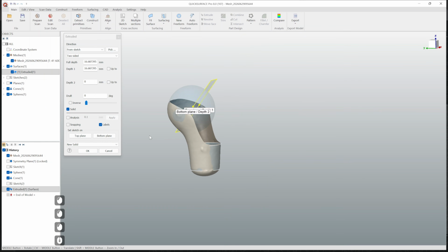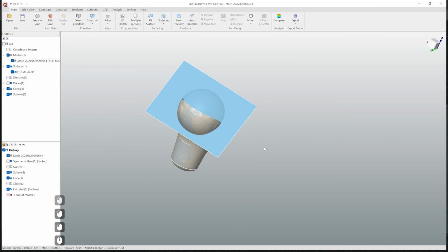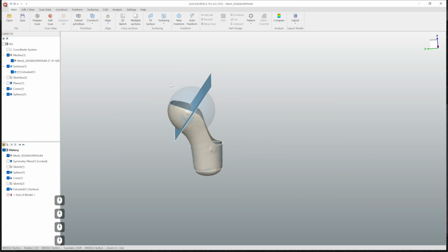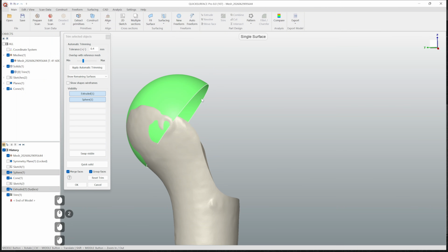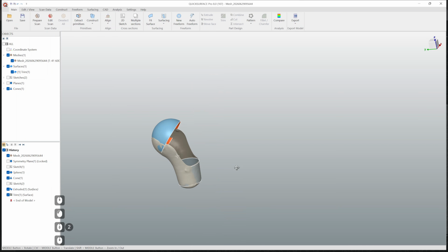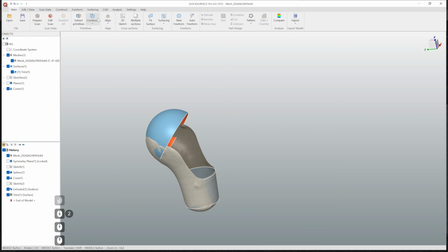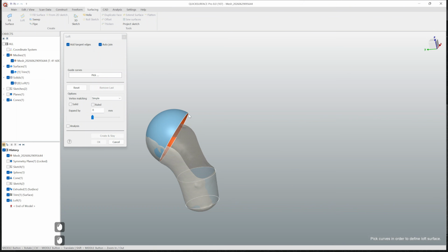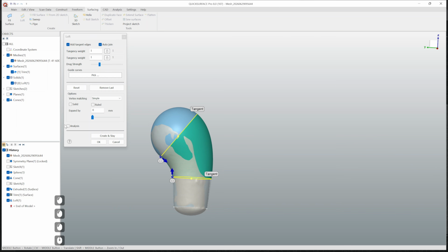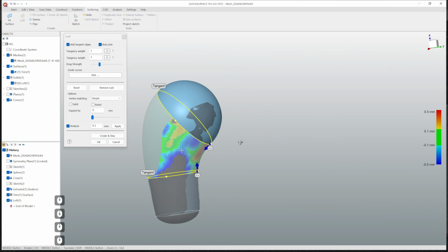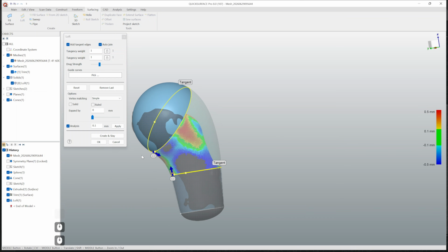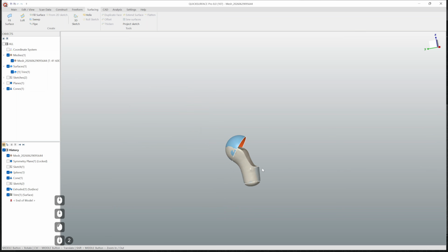Let's extend this line, extrude it to create a surface. And now let's just trim these two like this. Okay, so now I have two surface bodies, and now I want to create a loft in between them like this. Okay, and let's see the result. To be honest, it's not that bad. So definitely this approach could be used here.